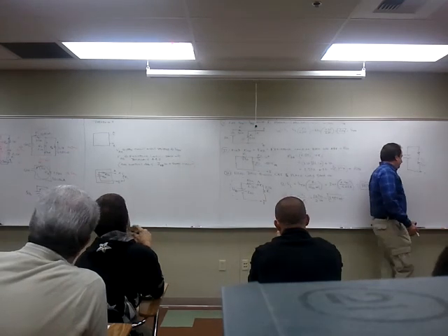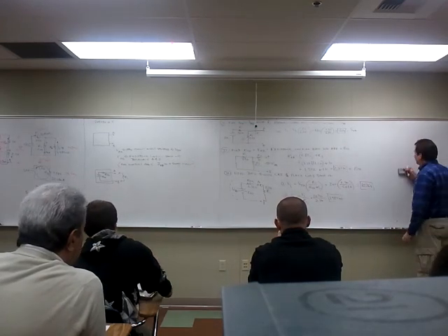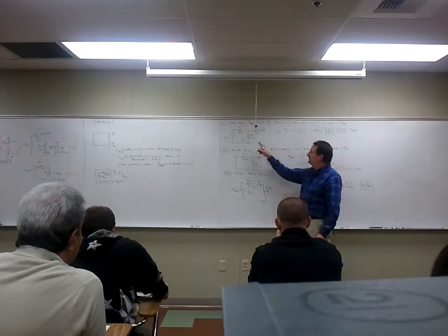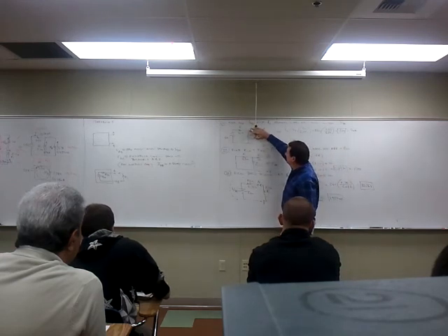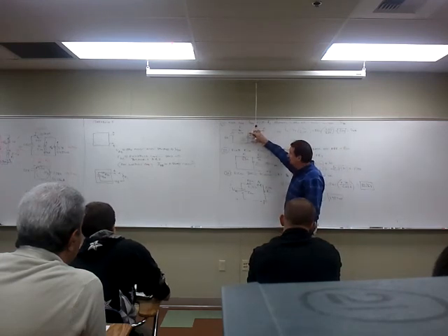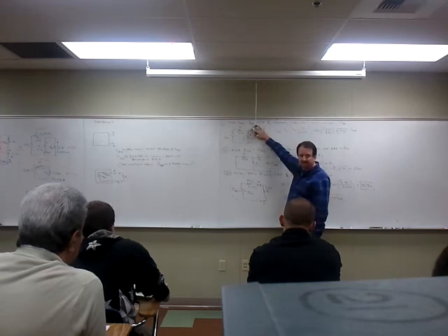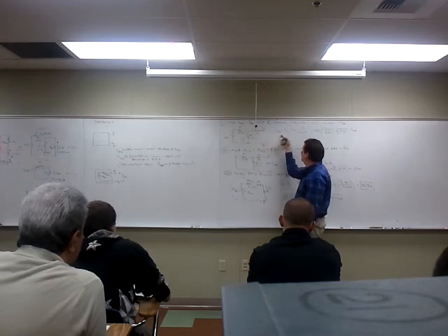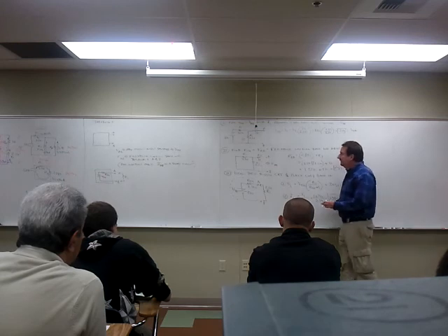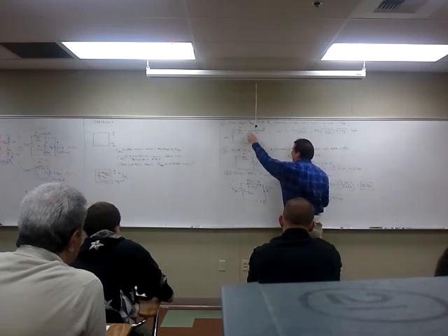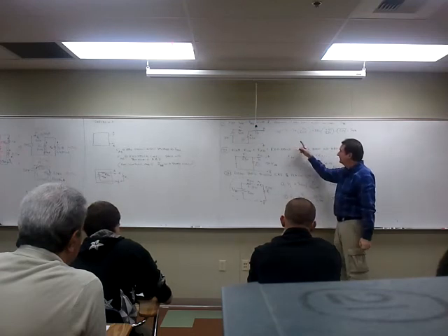Okay, so the open circuit output voltage, therefore, is simply the voltage drop across resistor 2. You can neglect this entirely. Isn't that a simple series circuit? Do you know how to find the voltage across the resistor in series? Of course. Now, I chose to use the voltage divider equation. The voltage from A to B is the same as the voltage across resistor 2, again, because this has got no voltage across it, so it's the same.